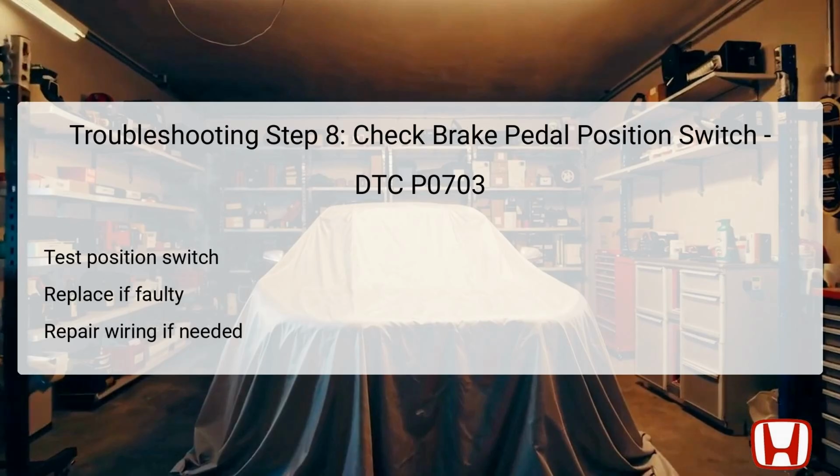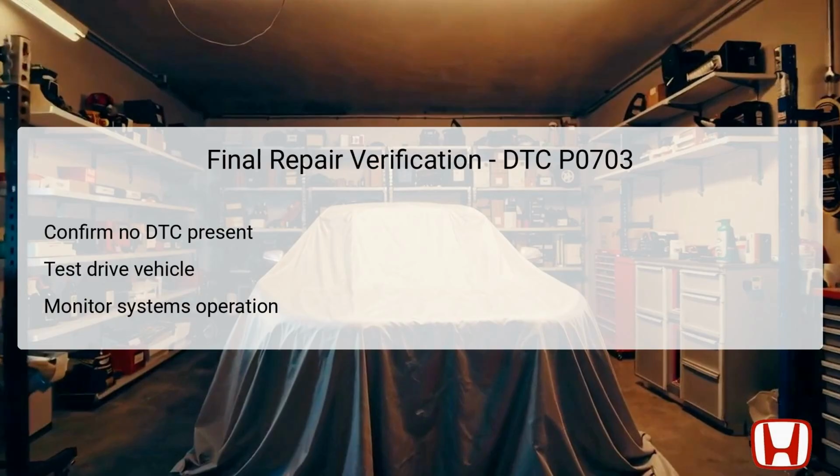Ensuring that you have a correctly functioning brake pedal position switch is crucial, as any faults here can lead to persistent DTC P0703 codes and ultimately affect vehicle performance and safety. After completing all necessary repairs concerning DTC P0703, it is important to perform a final verification to confirm that the issue has been resolved. Start by ensuring no diagnostic trouble codes are currently present in the system. Utilize the Honda Diagnostic System, HDS, for this check.